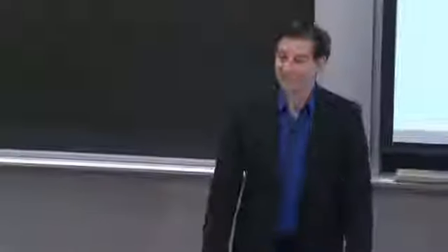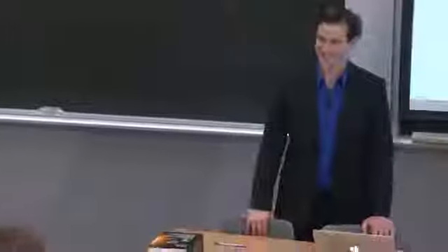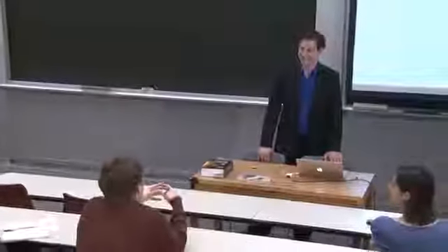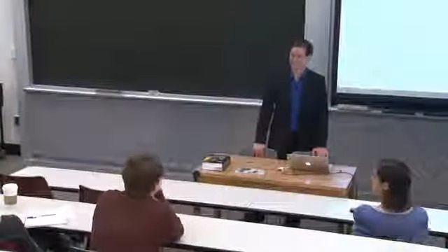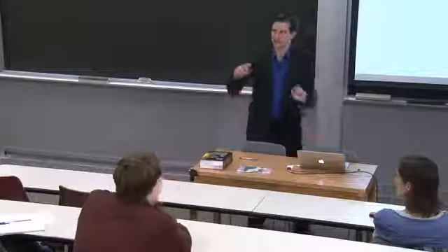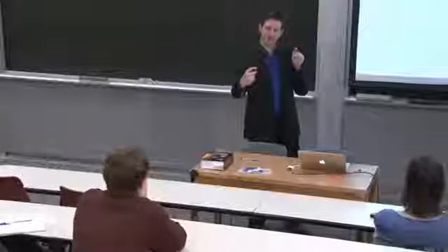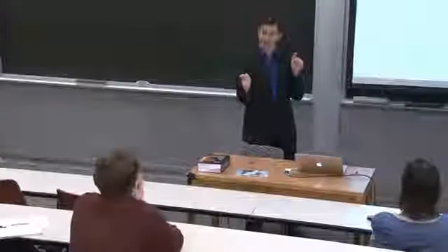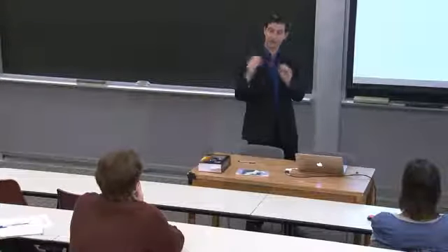Yeah? I have a question about carrier collection. Sure. How is it possible to extract any energy from carriers which are generated in front of the junction? Because even if they diffuse into the junction, they have nothing to fall down. Okay, so you have to think about it always from the perspective of the minority carrier. So if you generate an electron-hole pair, your minority carrier is now a hole in the n+ region. That hole diffuses across the junction, the electron stays.